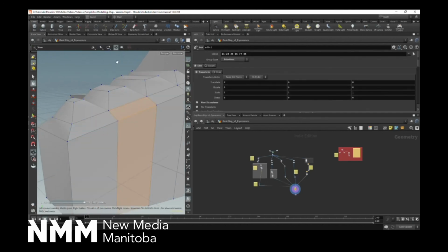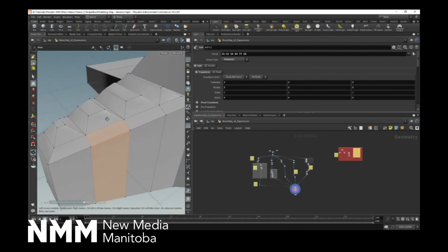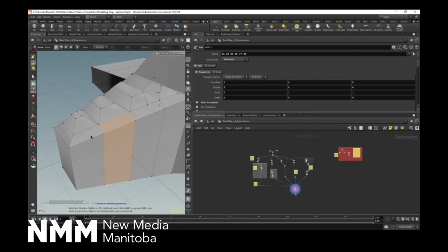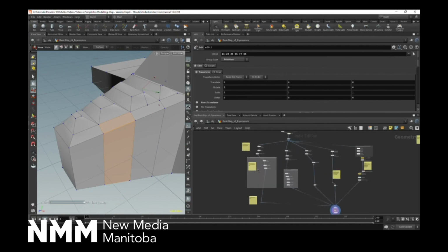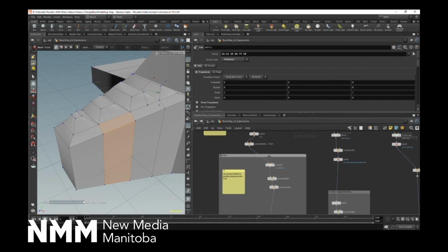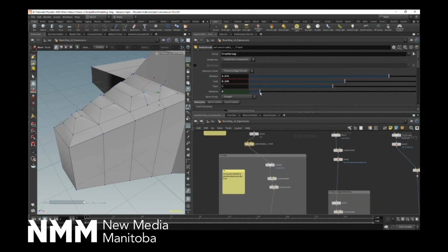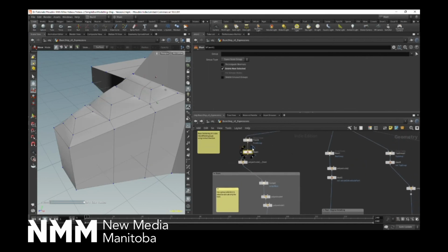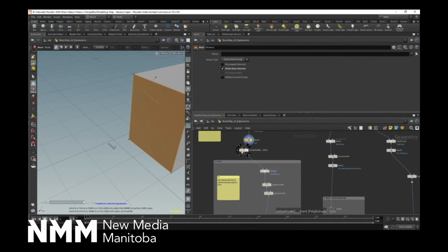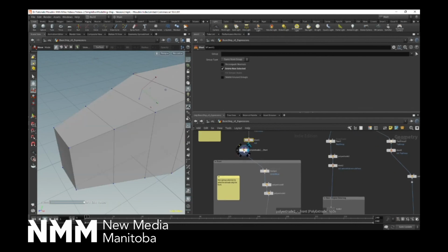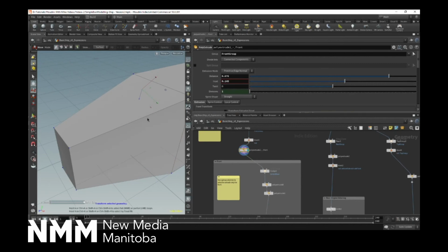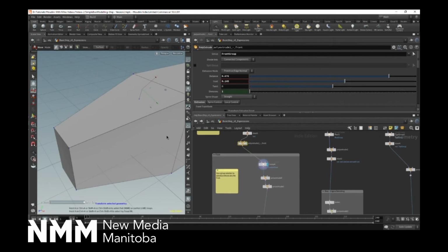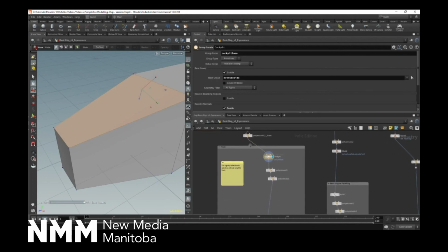But I wanted to give it this kind of detailing, and I was trying to figure out how I can control how many little cockpit beds I had. And I realized it was actually a really simple answer. I just had to change my extrude subdivisions here. So what I'm doing, again, remember from last time, I'm selecting this face, I'm extruding this base. And originally I just had one division. And then I'm doing a group selection.